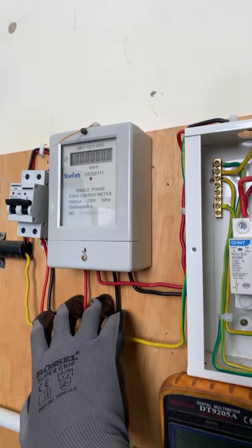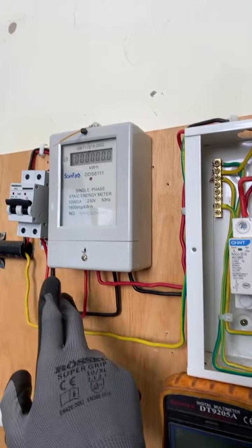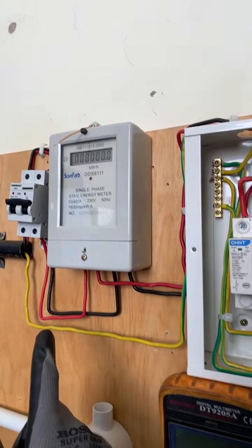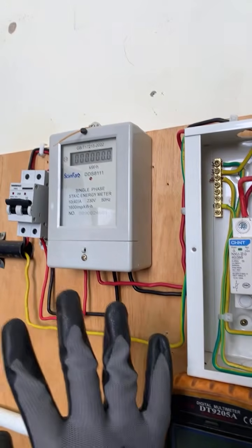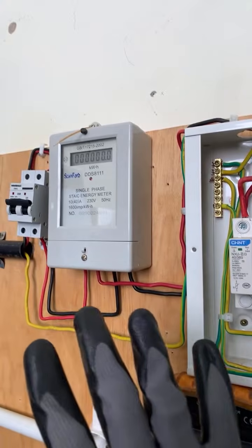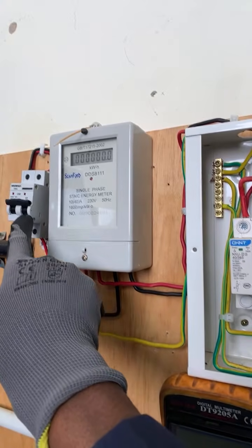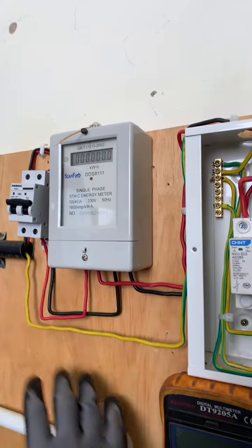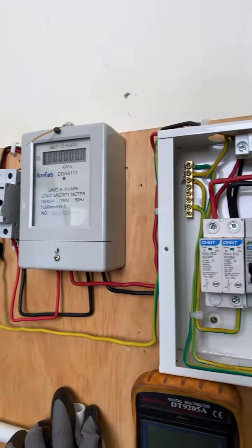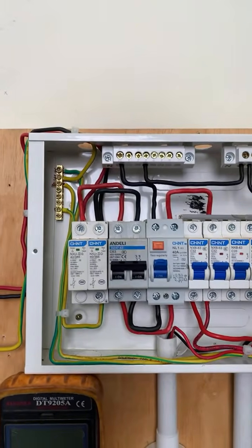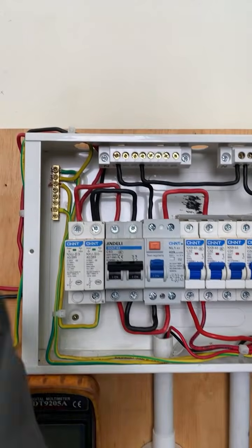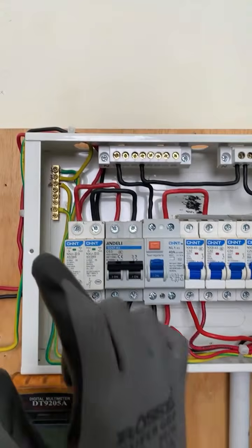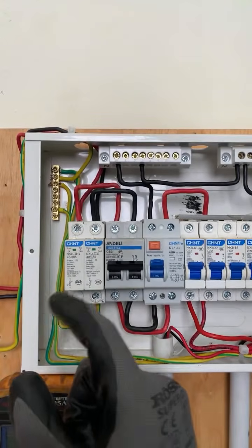Right? So if there's a loose connection on the neutral, that is why I normally say that neutral is king. The neutral should never be disconnected under any circumstances unless you are switching both the phase and the neutral. But you cannot disconnect the neutral only. Even at the transformer section, the neutral is very, very highly respected. You find that the fuses or the fuse carriers are only connected on the lines.